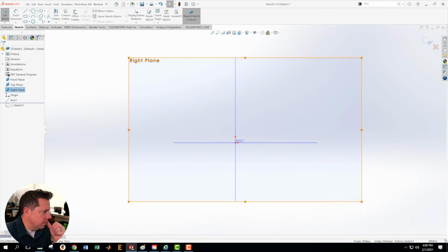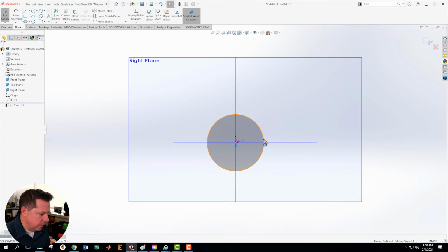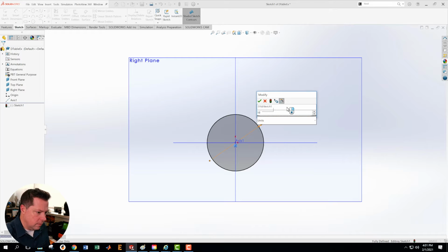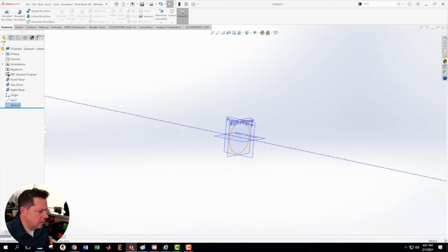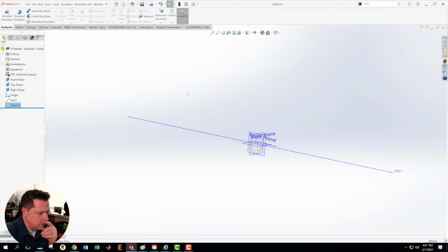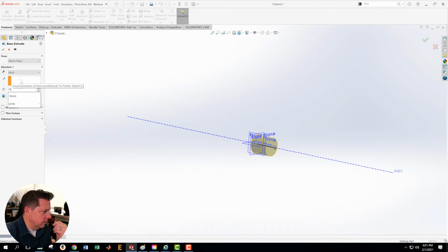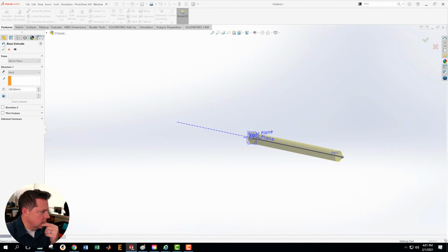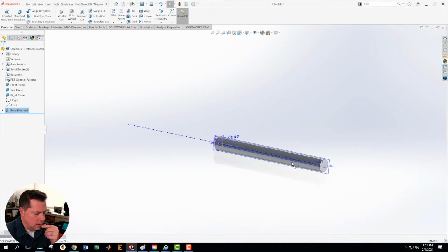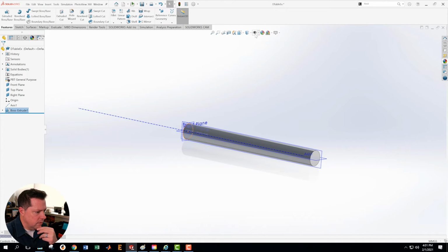And my basic default part, when I look at the guidebook, is going to have a diameter of 10 millimeters. Okay, that's good, fully defined. I'm going to take this shape now and I'm going to push it in just one of these directions and extrude it out there 100 millimeters. There we go. Okay, that's great. Then I'm going to add the chamfers on the ends.